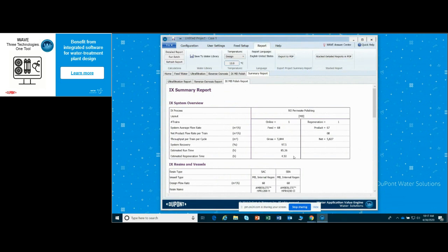I was thinking maybe you could just show at the top where that temperature box is in the drop-down of design. It might not be fully obvious, but once you've already run your design, you can go up and select the minimum design temperature and refresh your report, or even change to a specific temperature and refresh the report without having to go back and change all of the design conditions.